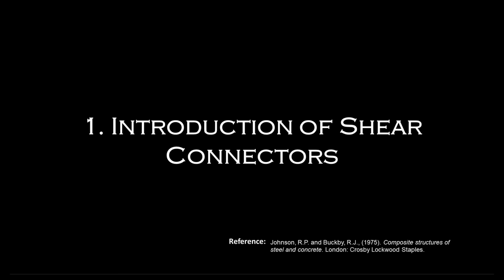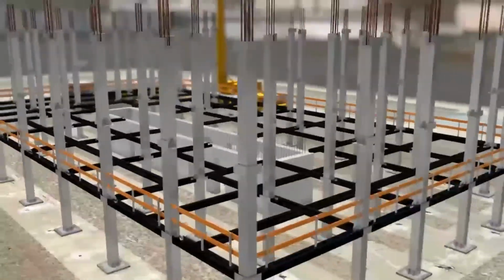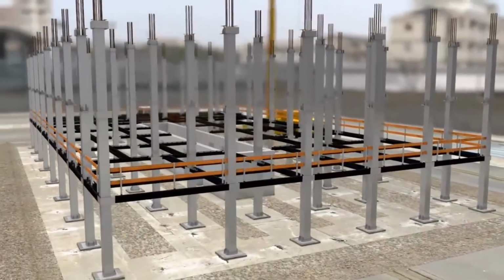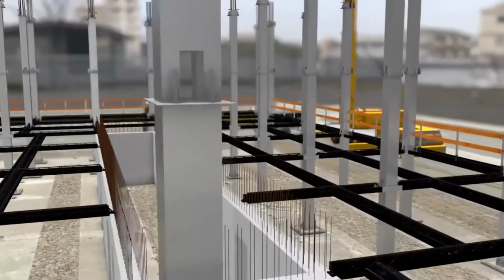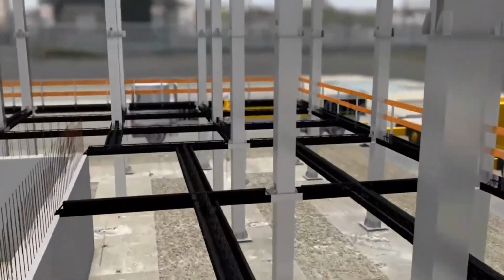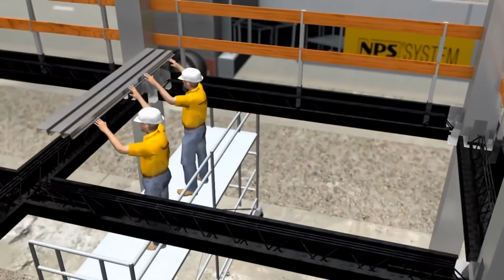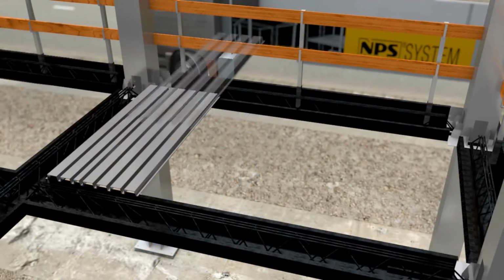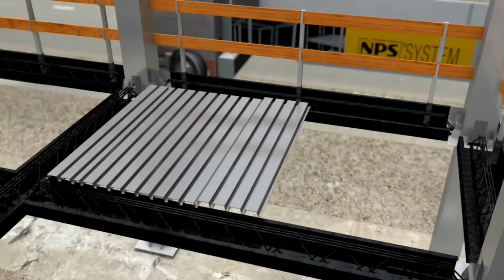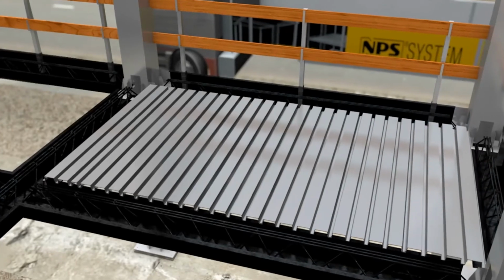The design of structures for buildings and bridges is mainly concerned with the provision and the support of load-bearing horizontal surfaces. The construction time can be saved if the floor slabs are cast on permanent steel formwork that acts first as a working platform, and then as bottom reinforcement for the slab. The use of this formwork, known as profiled steel sheeting, began in North America and is now standard practice in Europe and elsewhere. These floors span in one direction only and are known as composite slabs.